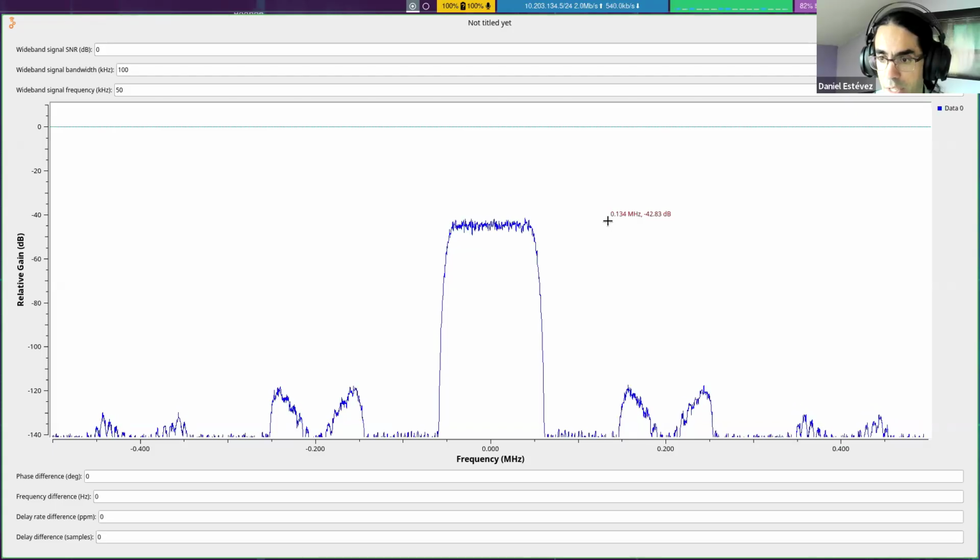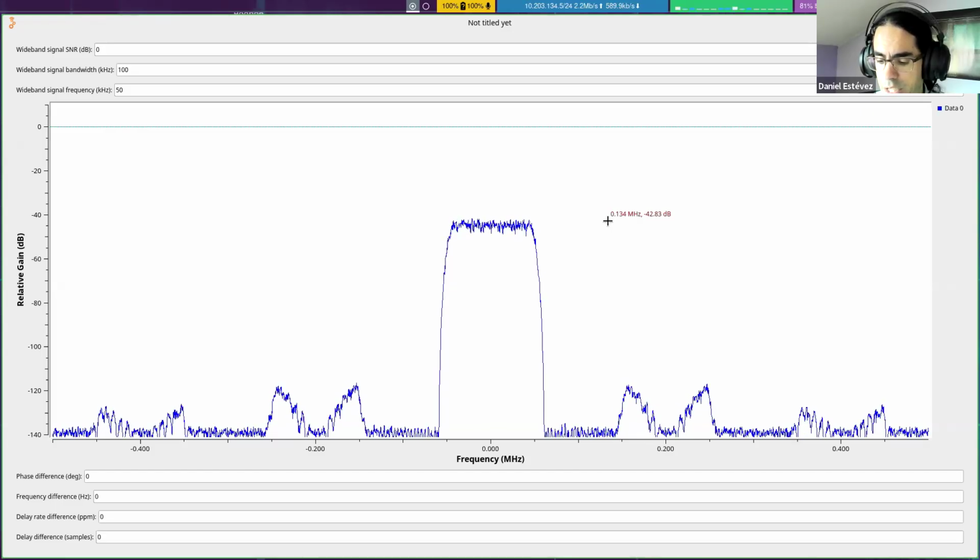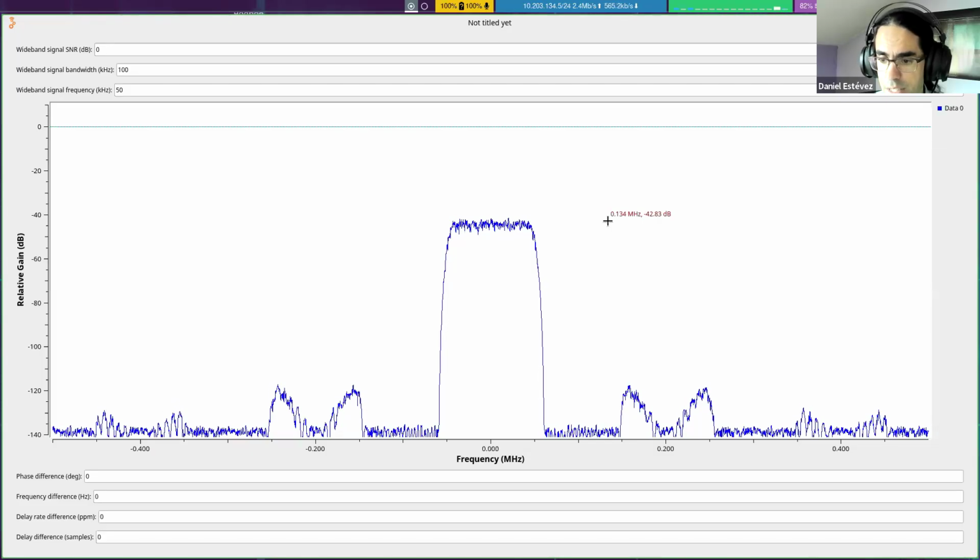We can measure the phase in degrees, for example, going from 0 to 360 degrees. And it's the same as with the delay because the wave doesn't arrive to the two antennas at the same time. The phase that the antennas are seeing is going to be different. They will be in different parts of these 30 centimeter periodic waves in general.